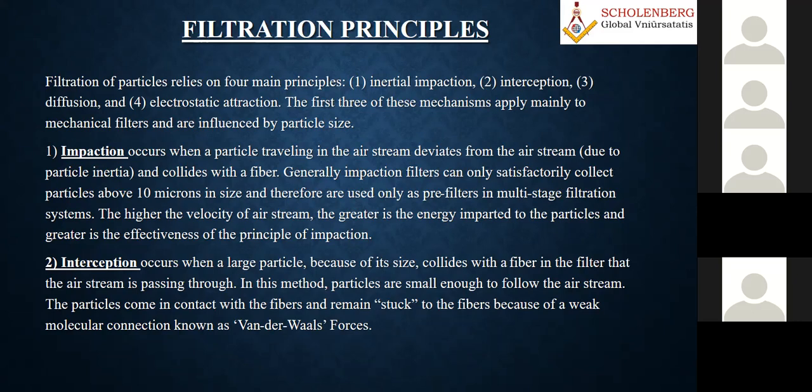When you go into slightly more detail on impact, as I told you, the particle traveling in the airstream deviates from the airstream due to particle inertia, isn't it? The moment it comes, something stops it here and it collides with the fiber. Generally, impact filters can only satisfactorily collect particles above 10 micron.